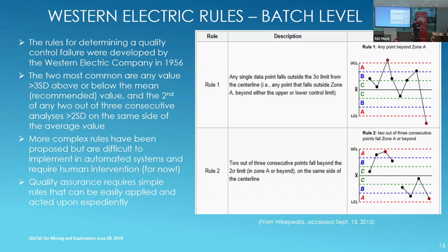And the whole 2 standard deviation, 3 standard deviation fail thing for standards and CRMs, we really would encourage people to not hit the panic button just because one sample's gone outside of 3 standard deviations. It used to be consecutive samples outside of 2 standard deviations.